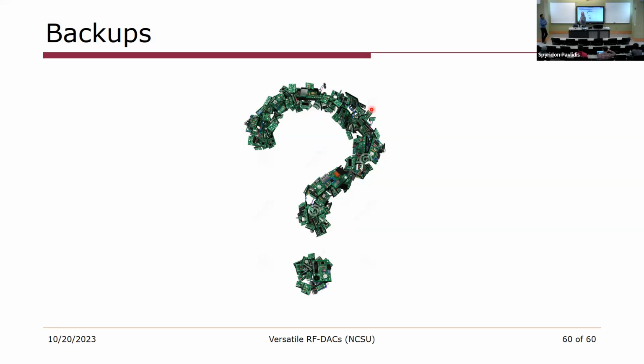So my student Ali, who's actually at Intel now, did a tape out at Intel in, I believe, 22 nanometer fins. And one of the things that we noticed was that our combination tended to favor smaller structures and more power combination, where we could make power combination out of overlay transformers that we could compact quite a bit. So there's a lot of work that's done in minimizing the loss in the network, and that really is making good practices: making wider metal strips, stacking metal where you need to, and trying not to have too many crossovers. That's actually where a lot of the loss ends up happening.